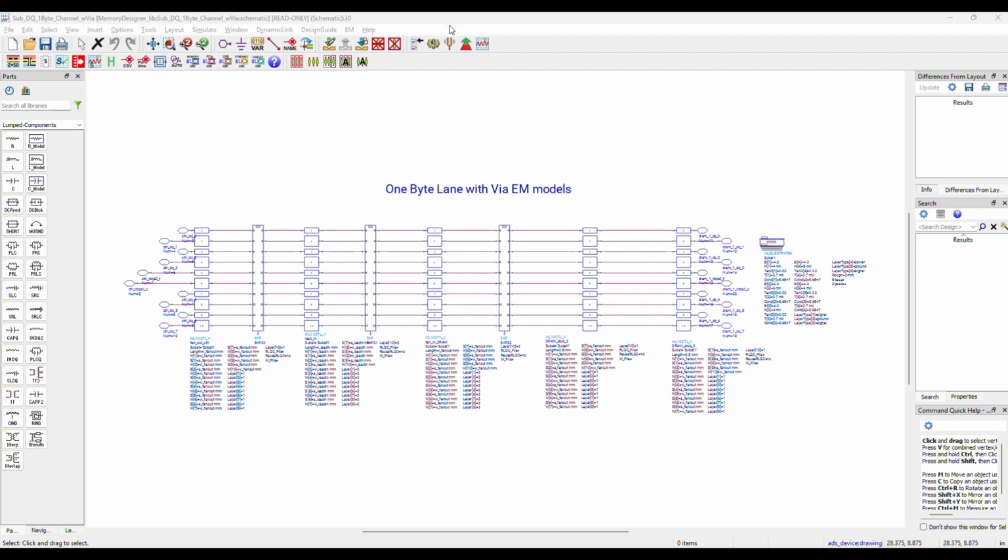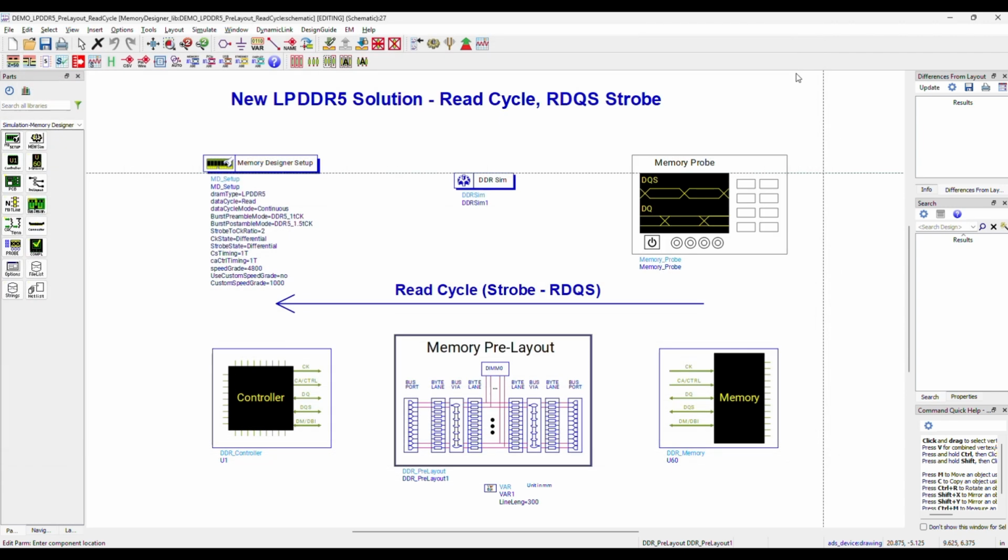As I mentioned earlier, if you want to perform pre-layout extraction for the traces, then you will use Keysight ADS CILD, that is Controlled Impedance Line Designer. And if you want to perform some sort of pre-layout exploration on your VRs, then there is a tool named Keysight ADS VR Designer. Now let's just close this pre-layout part.